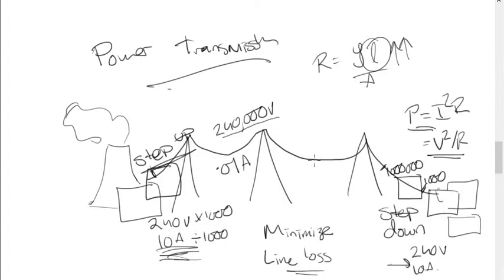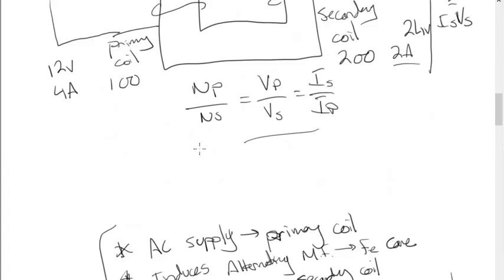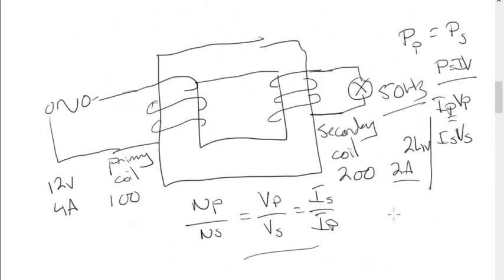Alright, I think I left out this one thing. That is, transformers case, why can't we use the formula V is equal to IR? Okay, বলতে পারবা? Because, yeah, it's two separate circuits. It's because V is equal to IR, তুমি যদি use করো, say you use V is equal to IR for the primary coil, it can't be applied to the secondary coil because they're two separate coils. They're totally two separate circuits.